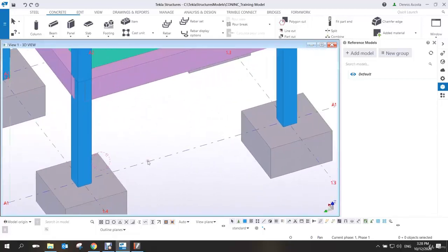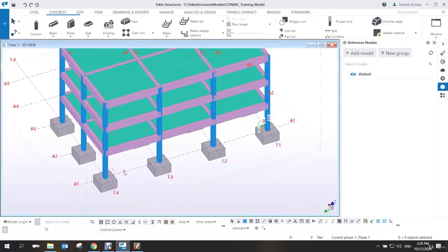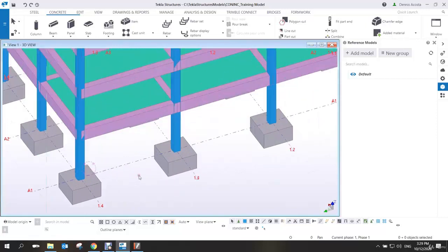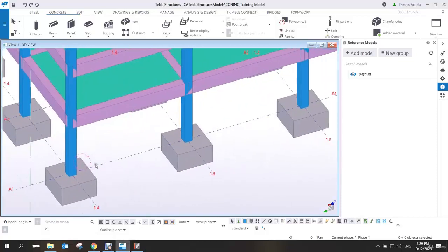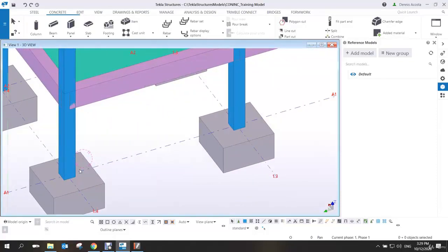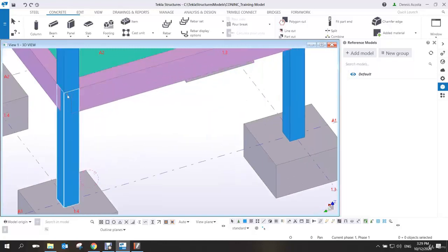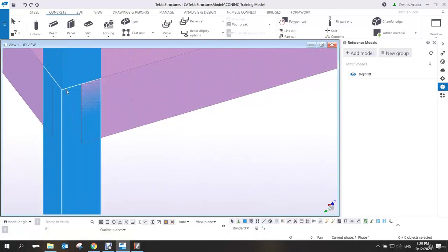For the wall, let's say for example, we want to cover the wall only on this level. We want to cover this wall, this part. So all I want you to do is create the wall outside the column. Okay, outside the column. So meaning the wall will be, let's say 3.5 as well, up to this point.